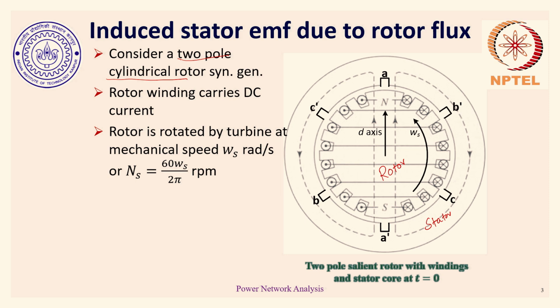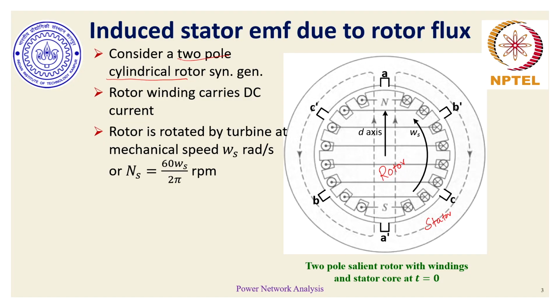Unlike my previous lecture discussion, where I had marked 120-degree phase stator slots and each of those slots was associated with one particular phase, here I am making a little change: there are certain sets of windings which refer to phase A, and they may be the path 1 conductor for phase A, and then we have A dash, which is the return conductor for this particular stator slot, so that continuity in the stator armature currents is maintained. And similarly, we have B dash and C dash referring to phase B and phase C stator windings respectively.